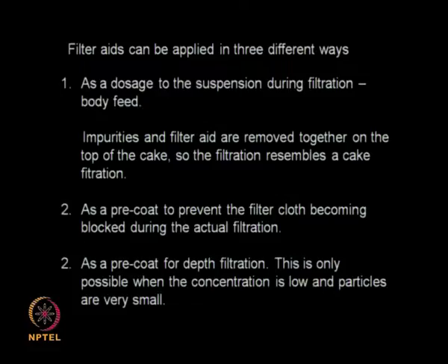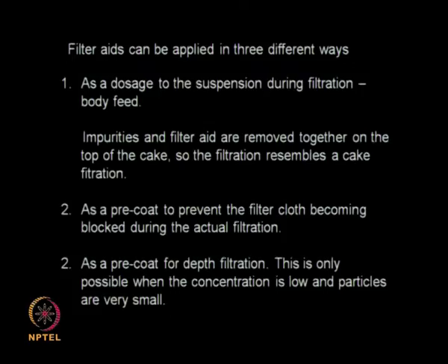The second approach is to use it as a pre-coat. Initially I will just pass filter aid, so the filter aid settles on top of my filter cloth or filter medium and then your biomass or the solid starts settling on top of that. So the filter aid does not block the holes in my filter cloth or filter medium. That is called pre-coating.